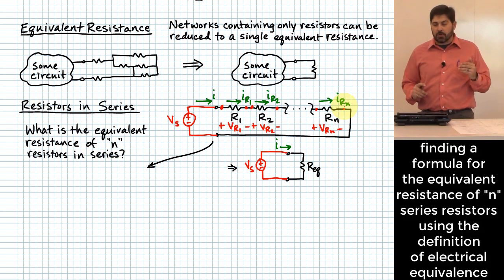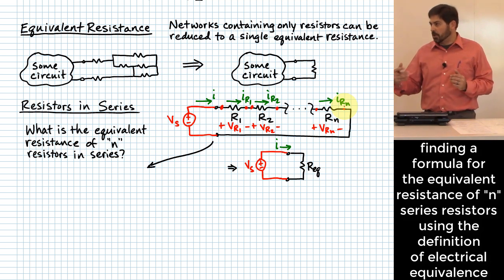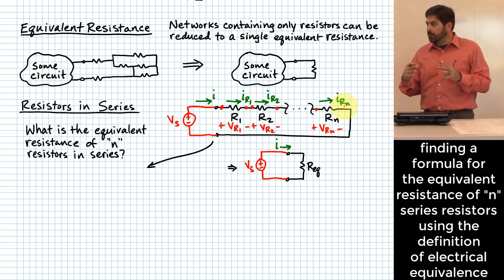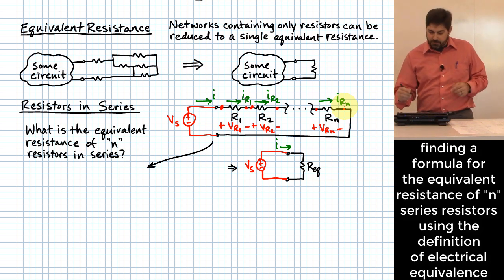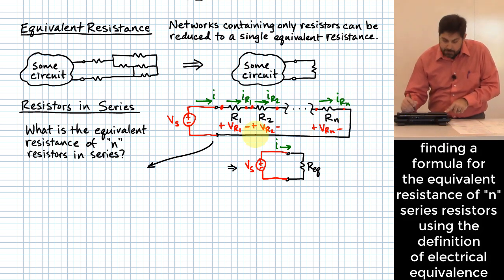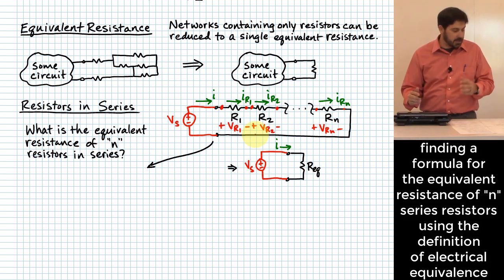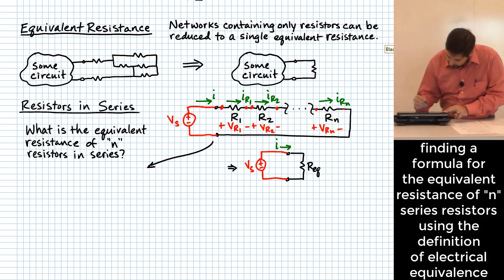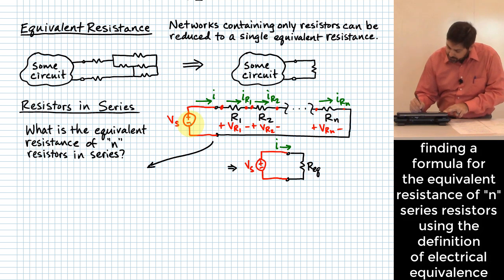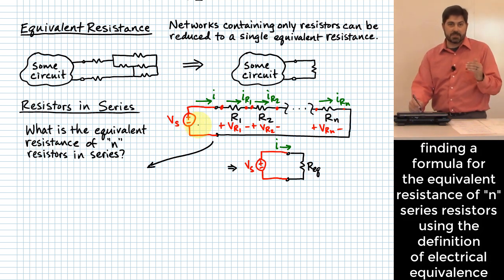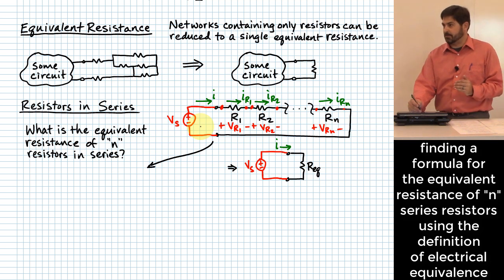I mentioned we are going to be using Kirchhoff's voltage law. Well, we're perfectly set up now to use Kirchhoff's voltage law for this big loop that represents this circuit. Let's count voltage increases as negative and voltage decreases as positive.